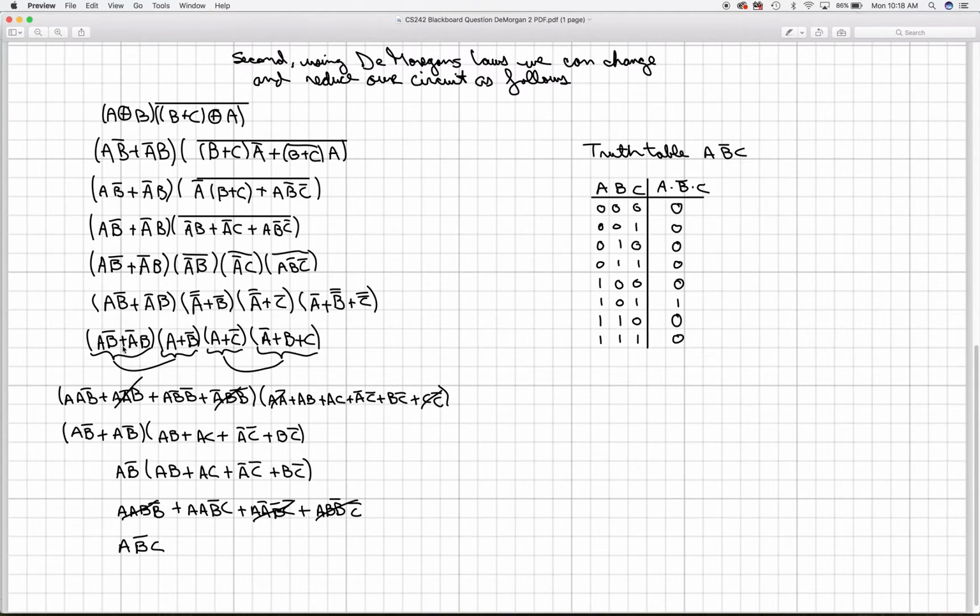All right, so over here, this A B NOT is going to be ANDed with A, so that's why we end up with this A B NOT. Then this A B NOT is going to be ANDed with B NOT, and so that's where we have A, actually I did this part in first, A NOT B, that's this right here. Then it looks like I did this A B NOT ANDed with B NOT, and so that's this over here. And then we'll do this over here, A NOT B NOT, and that's this part over here. So I put a parens over here because this is going to be ANDed with the result of this. This is the result of ANDing these two.